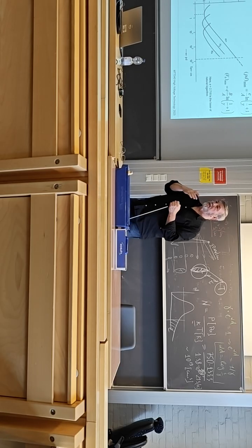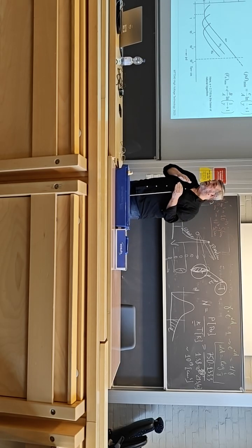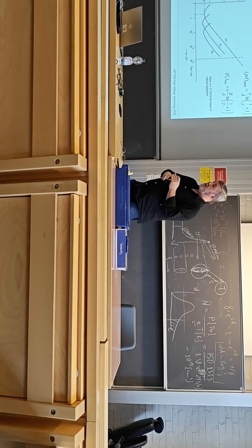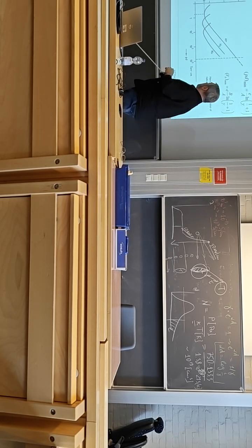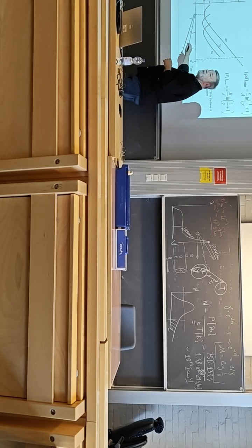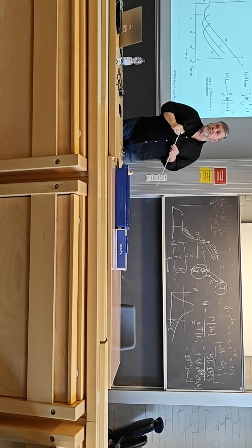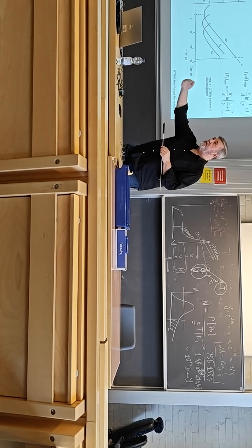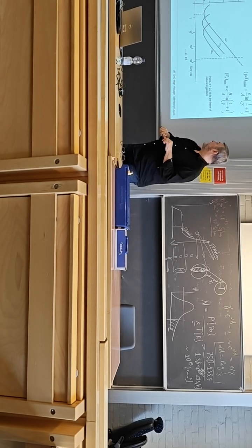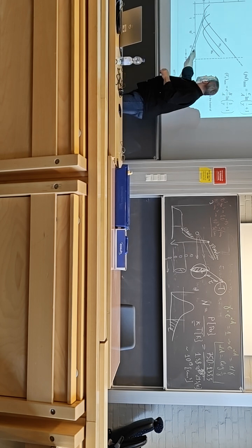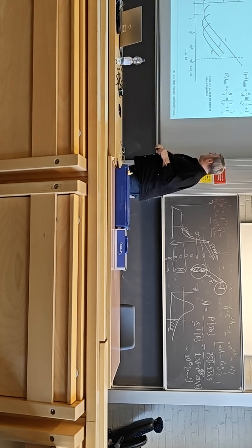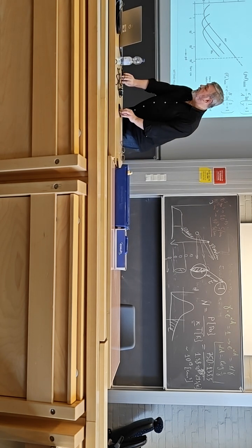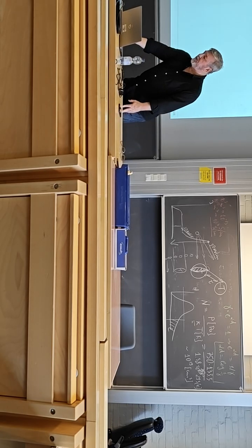At some point, you arrive at conditions when there is nothing to collide with. And then it comes to vacuum breakdown, which is a different story and is all about the injection of particles from the surfaces of the metallic bodies. So here are ideal conditions for energy transfer between the impacting particles and the accepting particles, so for ionization. So that's the explanation. Okay, let's take a break, and then I will continue with the other things.